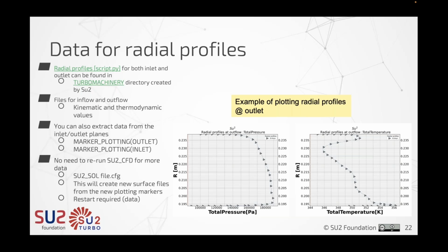For the convective gradients, I use Green-Gauss, but I have also used weighted least-squares. The differences are not much, so you can go with either.